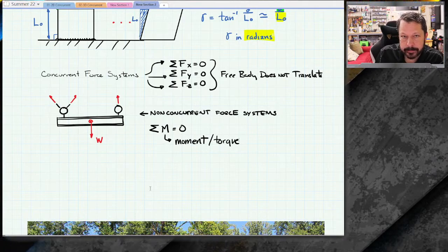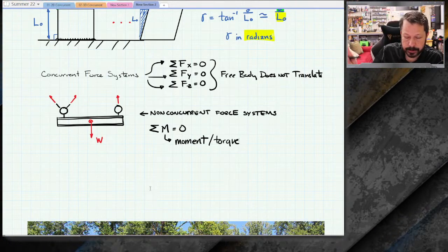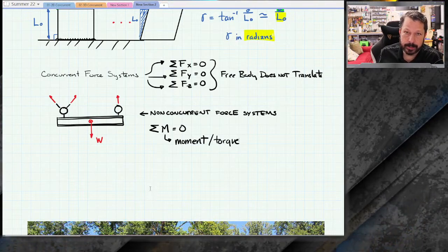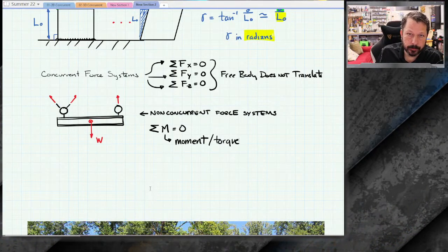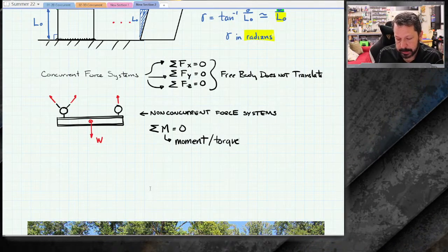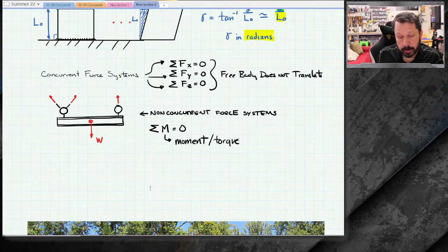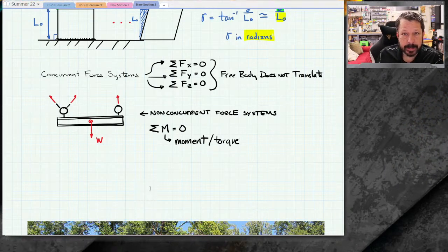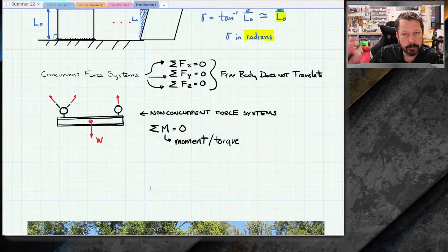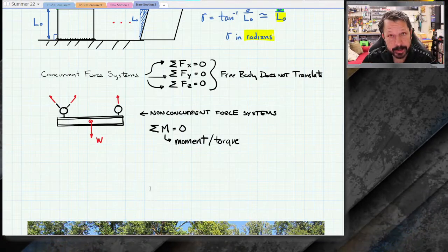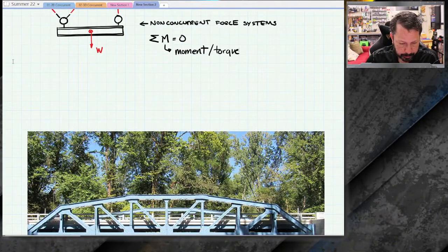We're really thinking of a planar surface, and the object, in this case our little I-beam, rotating in that plane. The summation of moments means that all of the forces that would want to make this thing rotate, not the forces, but the moments they create, have to add to 0. So we need to be able to calculate a moment.